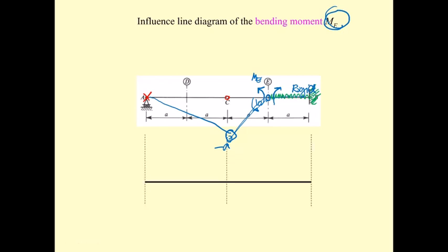Okay, we move it like this. B is fixed. Okay, C hinge, A pin, and we put an additional hinge at E to eliminate the resistance to M sub E. We put the M sub E into it. Okay, and then M sub E here produces nothing, only M sub E here is going to rotate this element. Since this one is A, this is 1, this is minus A, you get this. Okay, and minus A, you get this.